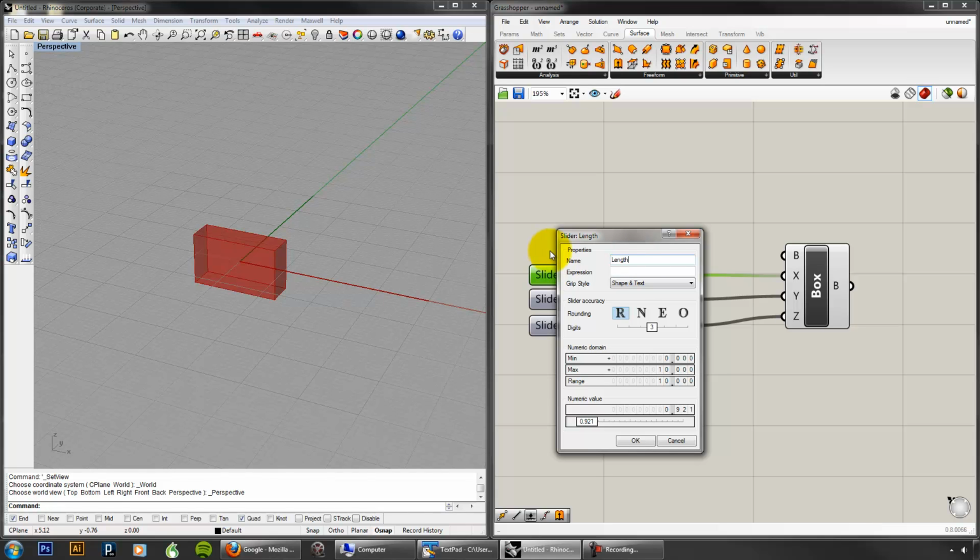And names are really important for variables and for parameters, okay? You need to give that variable meaning. Otherwise, it's just slider, and it's just a number, okay? Giving it meaning is helpful because as you work on these, you're going to start to forget what you were doing. You might come back to it later, and you don't know what that slider does. If you give it to somebody else, they're not going to know what it does. So names are very important. You need to choose them carefully, and you need to make sure that you always use them, okay?